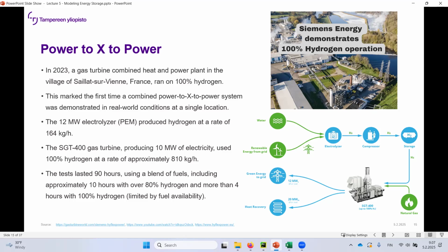And from what I've been discussing with the people that are running or testing electrolyzers, there is a possibility that it can be yanked on and off for a while. But in the long run, most likely that's going to be destroying the electrolyzer. So you have to run it throughout the year, and the running has to be a bit smoother than was anticipated. But for your question, can it be a small system?